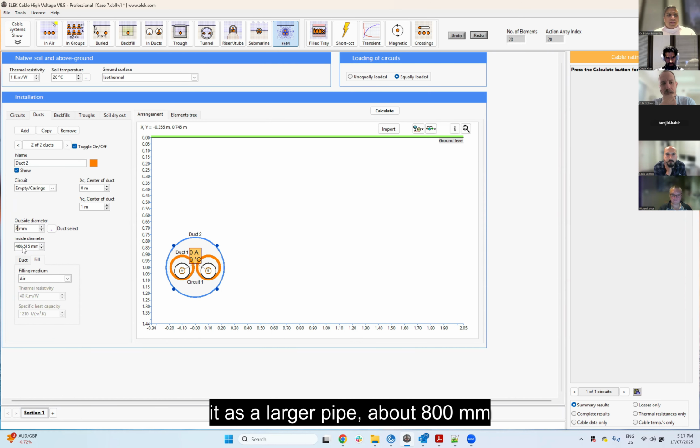As per TB880 and others, it's not stress limited. That's mainly because we have filled it with solid. If you filled it with air, it would go back to being stress limited. We have rounded down the current ratings here as per TB880 suggestion.